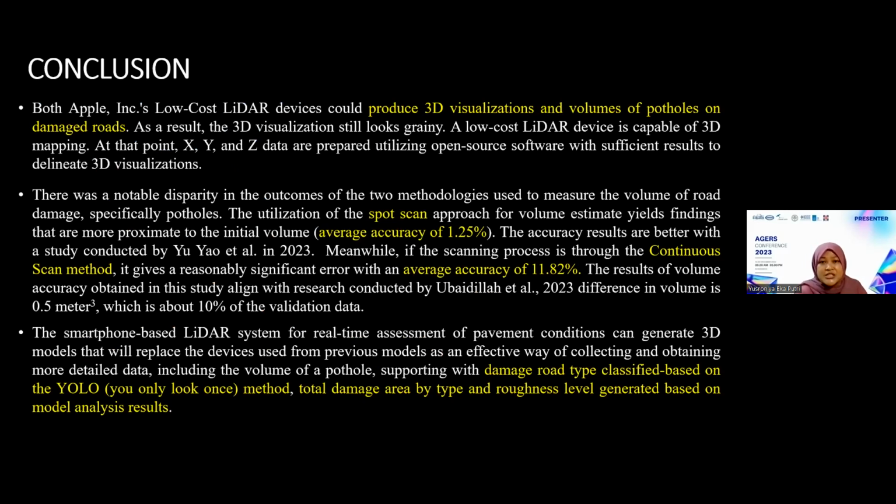About the conclusion, regarding Apple LiDAR, we can say low-cost LiDAR can produce 3D visualization and volume of potholes on damaged roads. The second is that the spot scan approach can get closer to the initial volume, with an average accuracy of 1.25%.